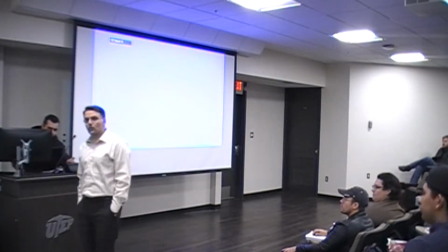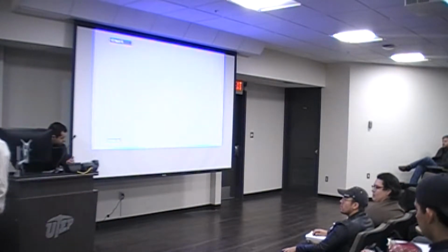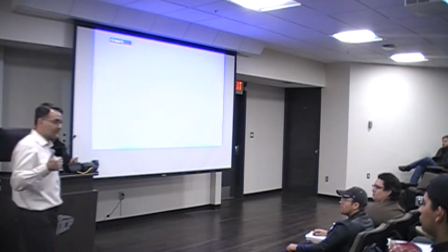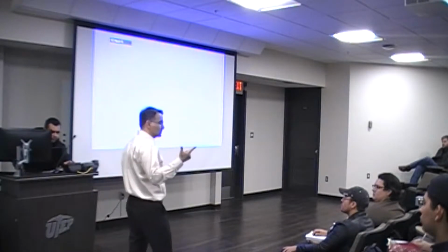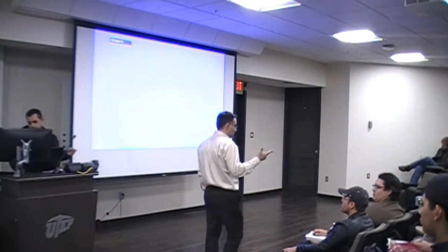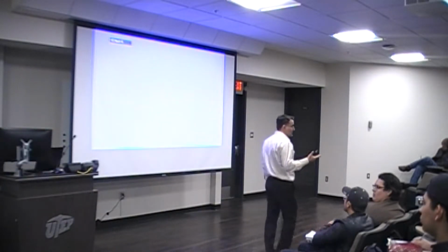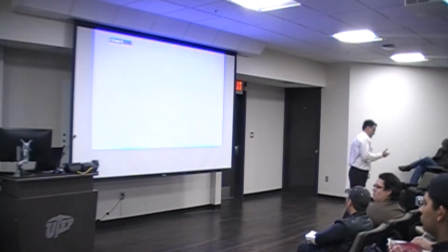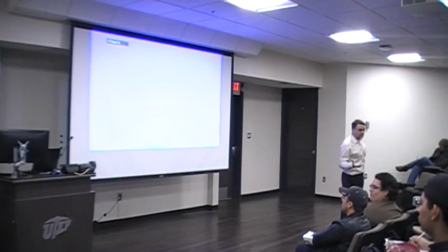But in terms of the soil, we're basically looking at an entirely different component. The first thing that we have to keep in mind is soils are stress sensitive. The ramification of that is the modulus value changes, the stiffness properties change. Also, we have to be careful that you cannot assign one modulus value. And soils are non-homogeneous materials, right?